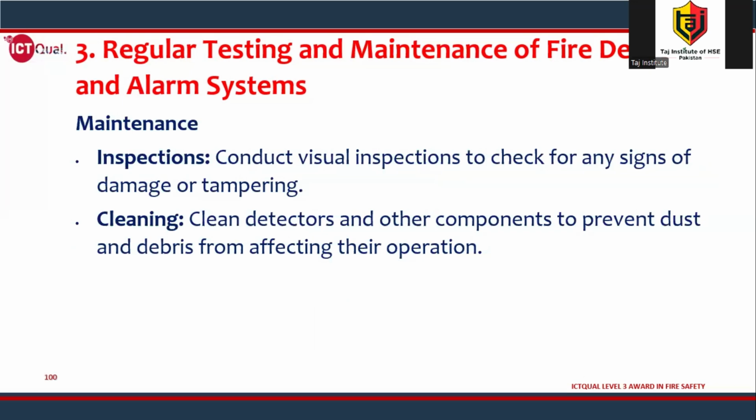Maintenance, inspections. Conduct visual inspections to check for any signs of damage or tampering. Cleaning. Clean detectors and other components to prevent dust and debris from affecting their operation. So this is also the main point. We have studied heat detectors, smoke detectors, and gas detectors also. So check them on a regular basis.